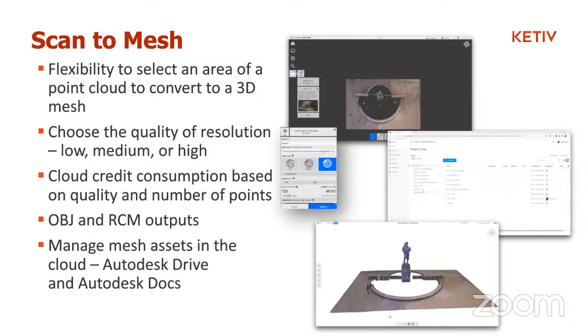The cloud credit consumption is dependent on two features. You can select the quality of the project you want to create, so there's low, medium, or high. And the cloud credit consumption is also based upon the number of points that you're trying to process from the point cloud. There's going to be two different file outputs that you can select, OBJ and RCM. And then you can manage your cloud assets on Autodesk Drive or Autodesk Docs.